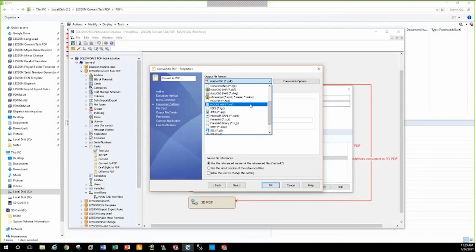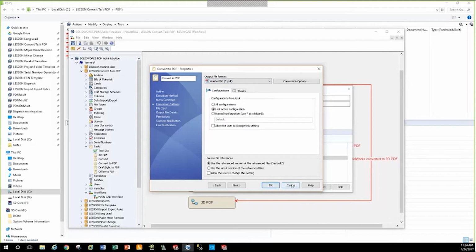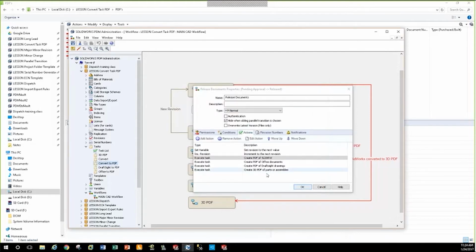Obviously, if we're doing some subtractive manufacturing, we want to make some chips, some CNC, somebody's going to make some G-code off of our parts, well, we can send out to the shop some parasolids, or we can send out some step files. If we're going to do some additive manufacturing, we're going to put to work one of those Stratasys printers, well, we can make some .stl files as well. So the Convert tool is a pretty powerful exporting methodology. It's not just about PDFs. Obviously, we're focusing on PDFs today, but I wanted to do a little bit of a segment there. So we're getting a taste of what the standard convert does. Let's take a peek at a couple of the other ones.